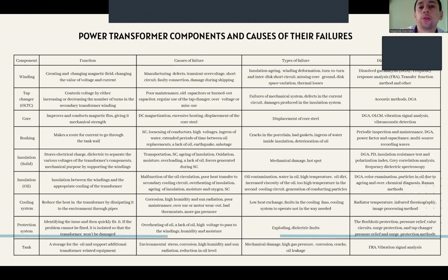According to the result of analysis of the cause of failure of power transformers, the failure of electrical devices occurs due to the effect of long-term short-circuit current that causes turn-to-turn short-circuits, burning, explosion, and geometrical changing of transformer winding.